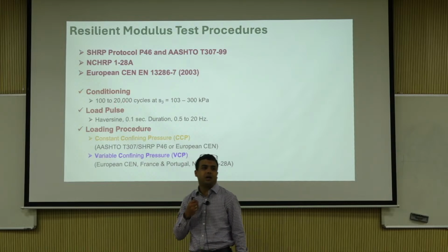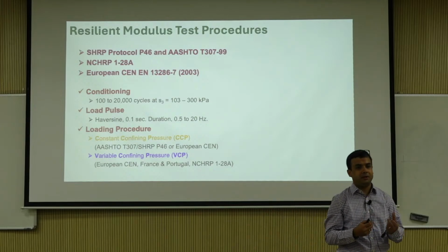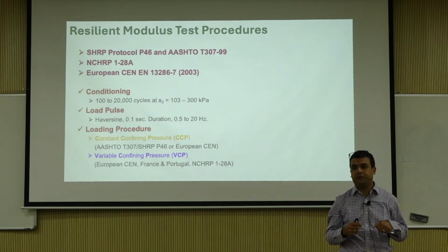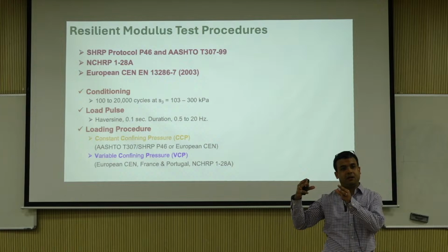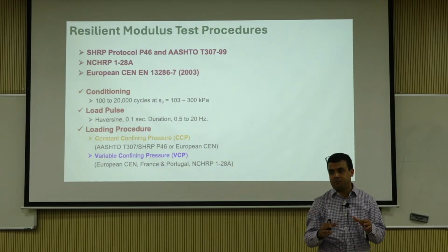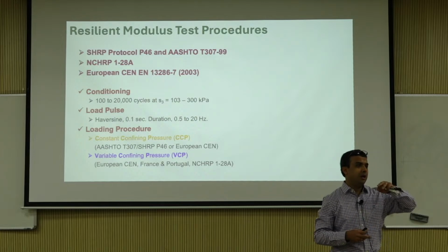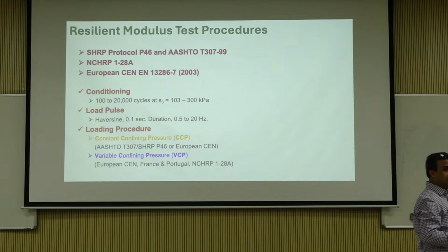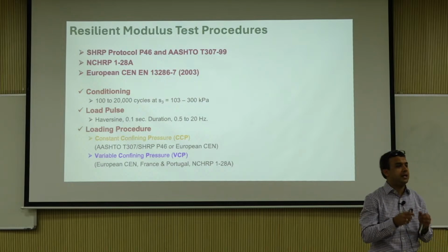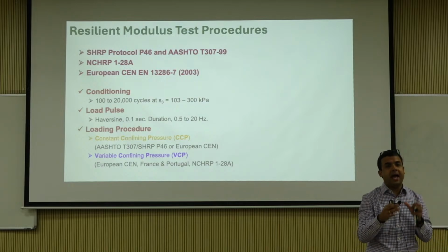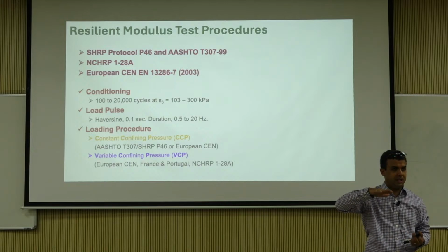First of all, conditioning. You have a reconstituted sample that you compacted in the lab, right? And then you're going to test it. So before you get into resilient response, you have to have your initial compaction done, right? What is that simulated through? That is simulated through your lab compaction, and for anything remaining you should be doing what is known as a conditioning stage.